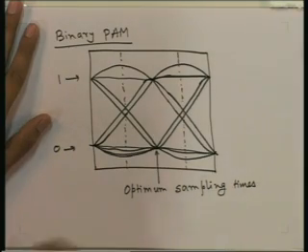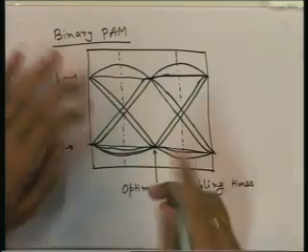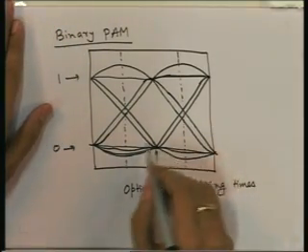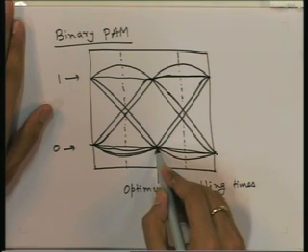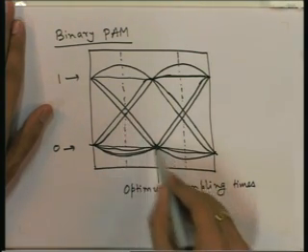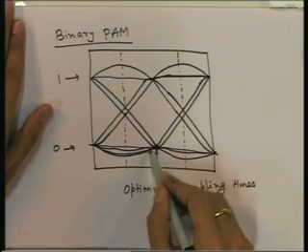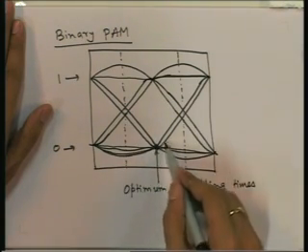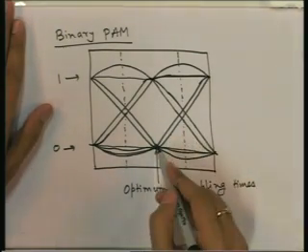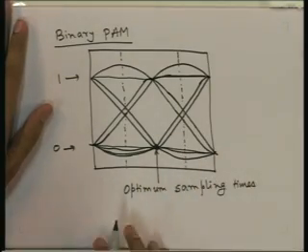Optimum sampling times, because this is unperturbed by the neighboring symbols. You can see that here it is always a point, or more or less almost a point. So, if you sample somewhere else, if the value was minus here, that is 0 bit, then its value will go up if you sample somewhere else. So, this is the optimum point to sample here, here and so on.